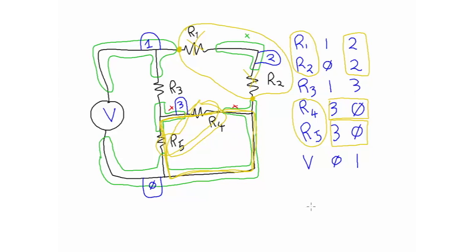And so any of these three methods is valid. Like I said, I kind of see the green node method as soon as I look at a circuit, and that will come with very little practice. But in the meantime, any one of these methods will help you recognize and check series and parallel.